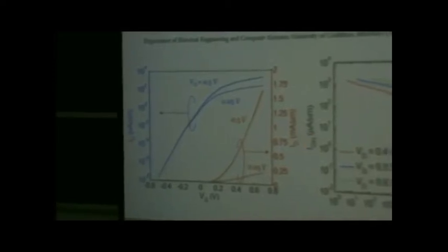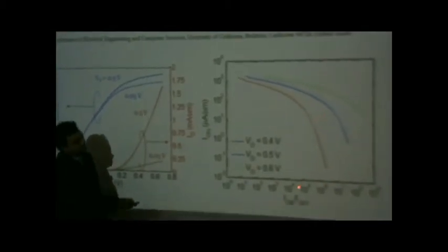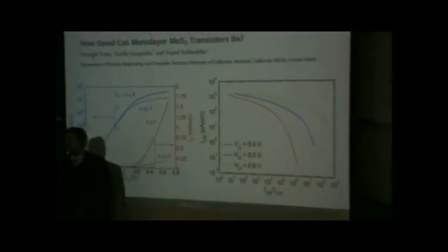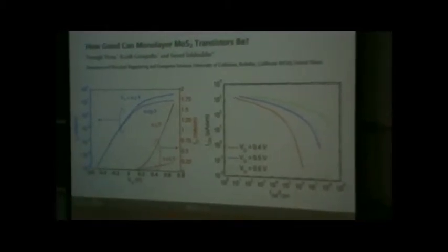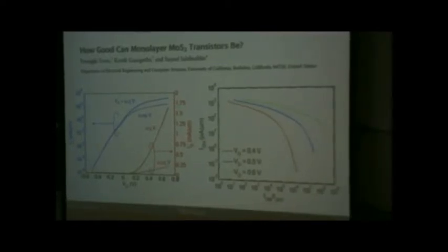What I mean by that is, when I plot I-on versus I-off, if I choose 10⁵ right here, I do not even hit a few hundred microamps per micron. That's the problem. And at this point, we realize that this is coming because of the effective mass.